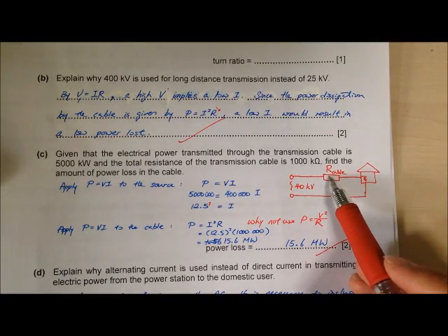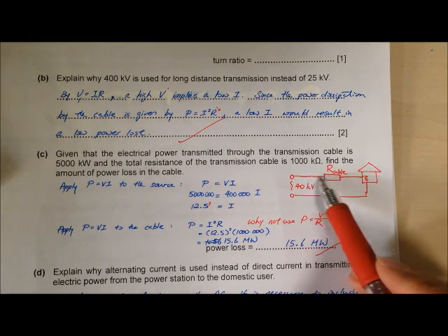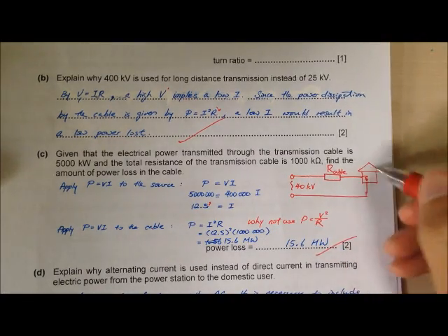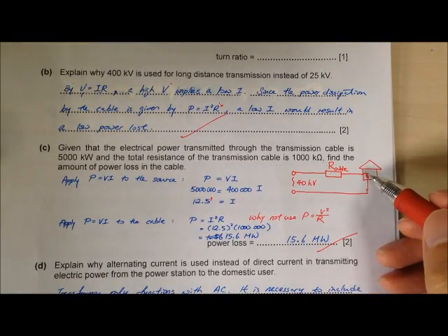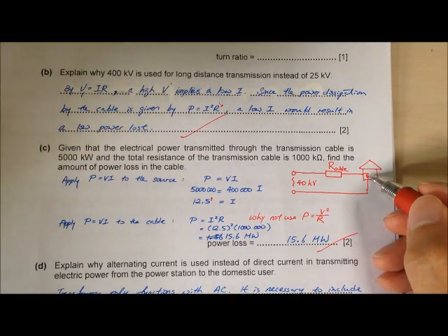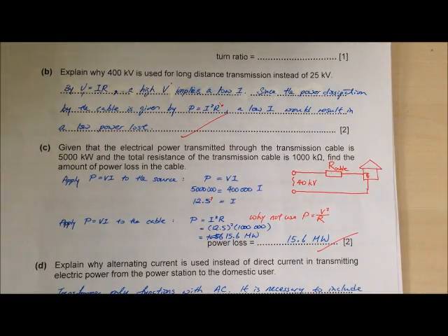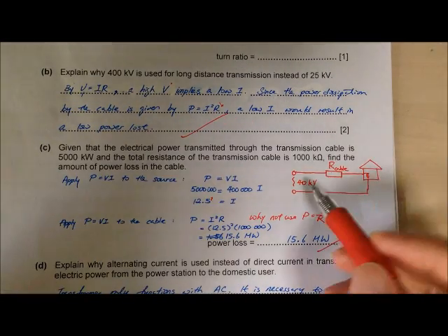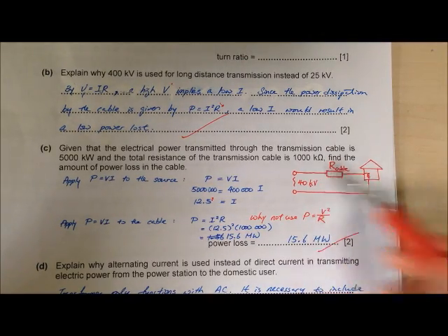your cable resistance is actually connected to whatever appliances in your house in a series circuit. Can you see? It's series, right? There's only one path. Even though yes, down here you branch out to a lot of electrical appliances, imagine all the electrical appliances, you combine all the resistance into one effective resistor. And this one effective resistor is actually connected to your cable in series. So what happens in series is that your voltage is being shared. So you cannot say that this 40 kilovolt is actually the potential difference of your cable.